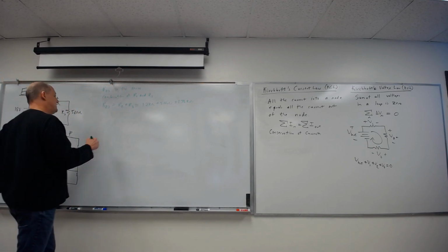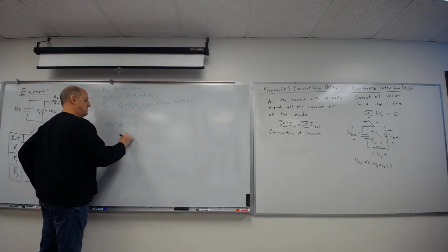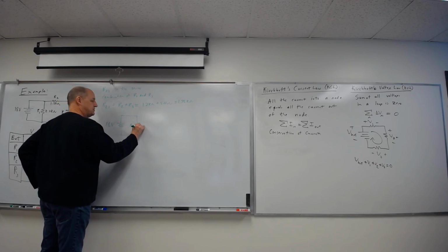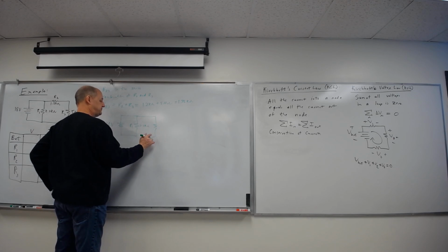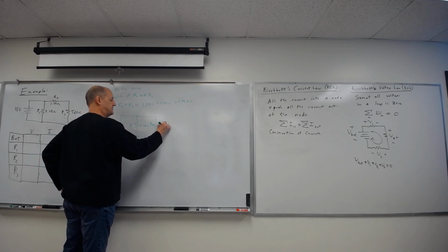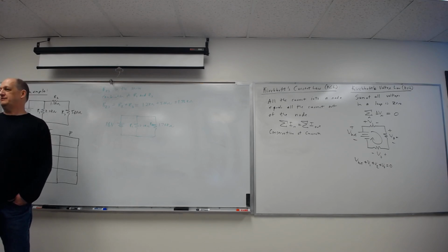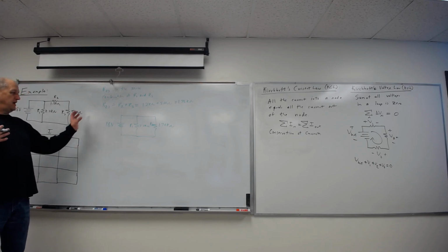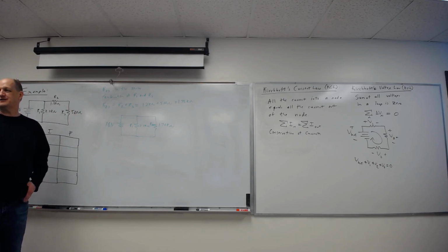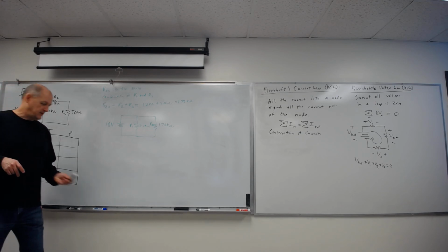So I'm going to redraw my circuit then. I have 18 volts. I have R1, which we said is 2.2 kilo ohms. I have these two combined in series, which is my R23, which is 1.76 kilo ohms. And now they're both in parallel. I'm going to go ahead and do it now. You can actually stop here. Everything's got 18 volts. You can go find their currents. Actually, let's go ahead and just do it that way. Are we okay with that? Better series down in parallel.